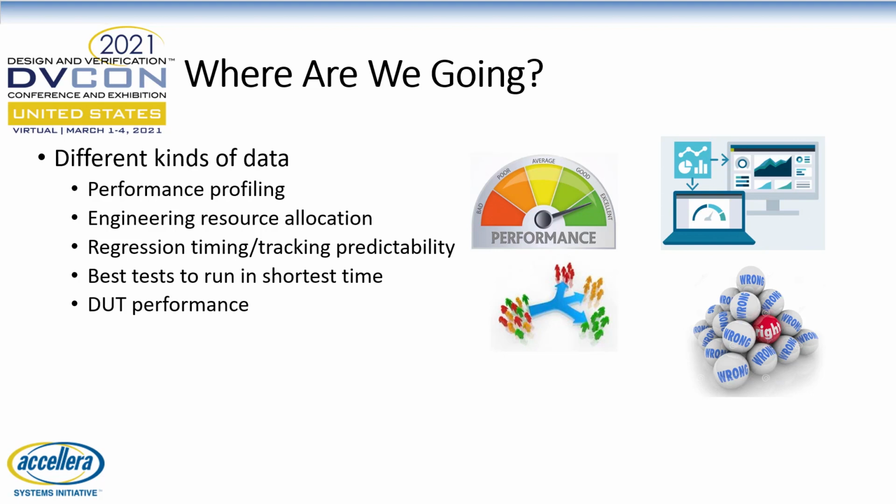And if you track how long your regressions take and track them over time, you'll be able to be more predictable in forecasting how long it will take you either to rerun tests when a change is made or to finish a given regression run. And by tracking other aspects of each test, you can quickly identify the set of tests to run that will give you the best coverage in the shortest amount of time, which is great for deciding which tests to include in a check-in suite.